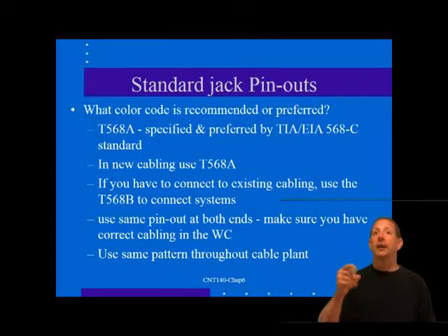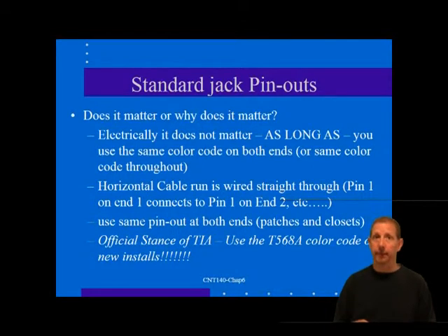There has been considerable controversy as to which pattern is the proper one to use. Depending upon whom you ask and where you ask, you can get some strong opinions on either side of the question. The TIA standard, however, is quite clear. The pin pair assignment shall be T568A. Optionally, T568B may be used, but only if necessary to accommodate certain 8-pin cabling systems.